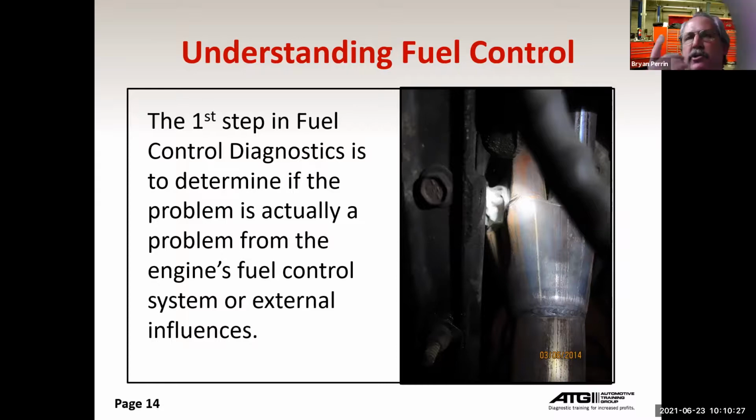I can actually weld things with a gas torch without even having to add any other material if I have good material. Like in the exhaust business, just for fun, because you do a lot and get bored, you find things to challenge you. We take two new pieces of pipe, where one slides into the other, and you'd normally weld around the pipe, feeding in a piece of rod, melting it and mixing it with the pipe and the inside pipe. You're mixing the atoms together. What we'd do is take these two pieces of pipe, not use any rod, and just get them flowing together and make a nice weld.